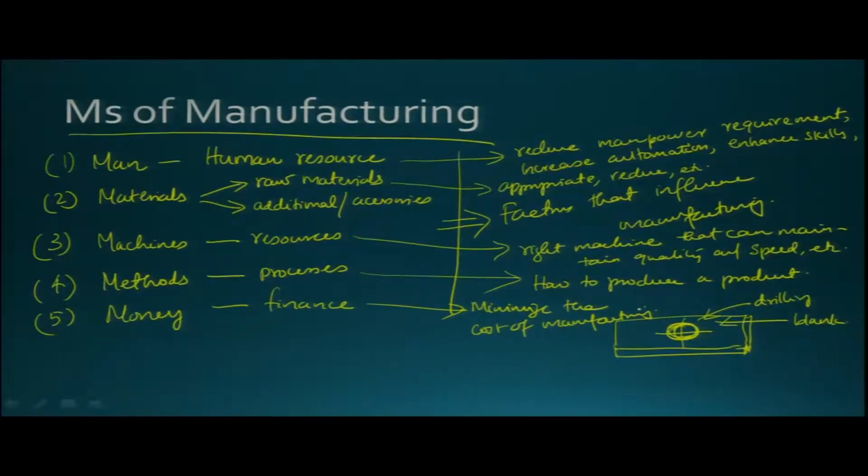An example would be that sometimes one of the most expensive things you end up using is the mineral oil or coolant when you are doing machining. If you are machining a very complicated part, then the coolant usage will also be pretty high. And at some point, let us say you came up with a nice method to substitute the mineral oil coolant with vegetable oil, which is cheaper, then that will reduce your financial requirements.